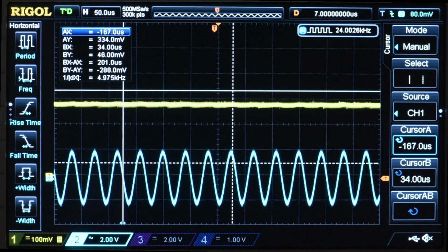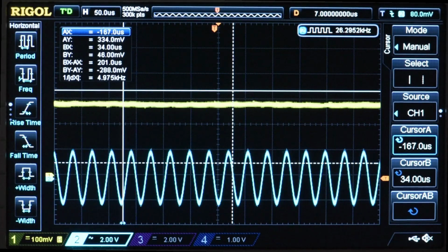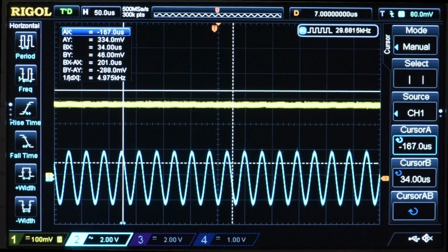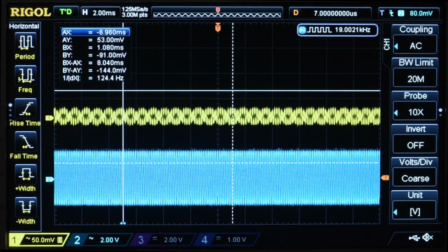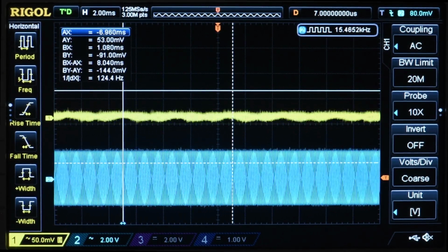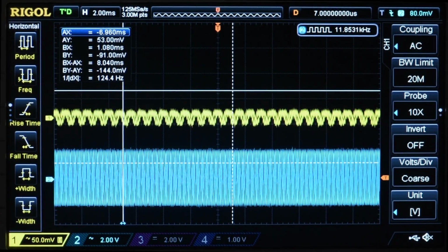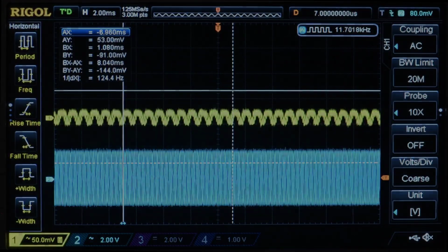And then it looks to drop around 24 kHz. And then maybe increase a bit. Here at low sweep speeds, you can see the low frequencies in the output and how it drops to about 0 at 12 kHz. Not unexpected really. I knew it wasn't going to be that easy.